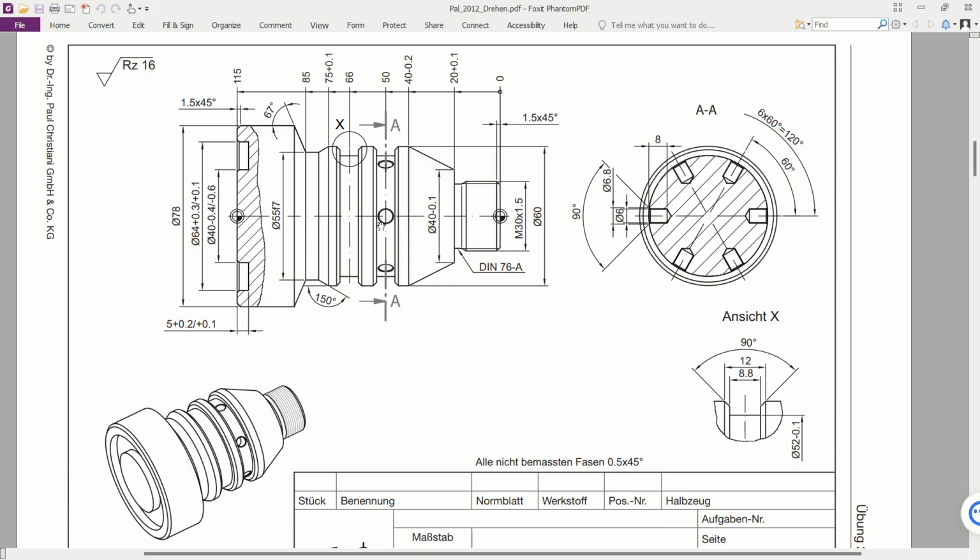I added some features. Here you see I'm doing a drilling, which is going deeper to 8 millimeter deep, and then I also added here. So I'll show you some commands on how to offset a new feature from here to here, and at the same time, how to add maybe a milling feature on a turning machine. Let's go to our program.